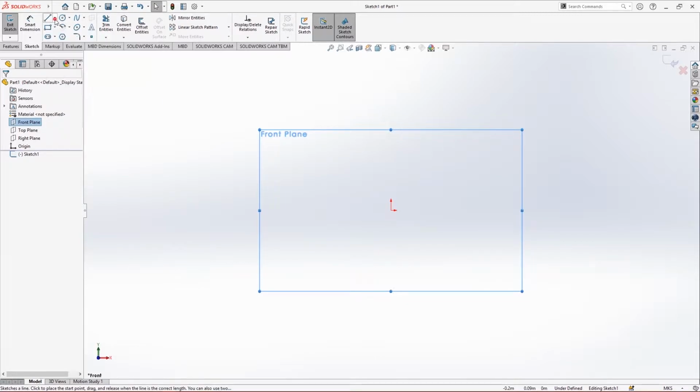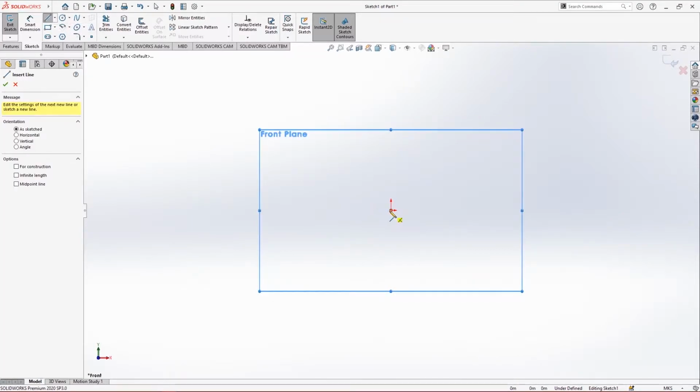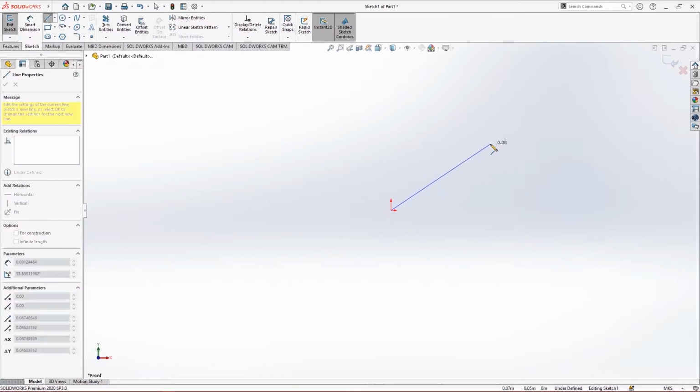When you click on the little arrow, it will tell you multiple ways to draw a line. The first one is a line, the simple one. Here what you do, you get 2 points of a line, the first one and the second one, then you draw a line. When you complete a line, you can still make a third point, then again it will draw a line between them, and then again a fourth one.